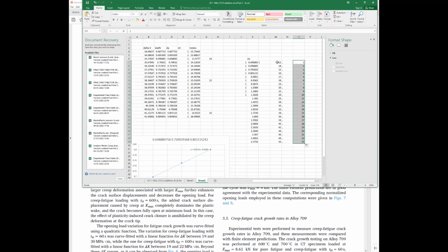So how we will do, we will release 12 elements, and then in step 1 we will apply the load to maximum, and then it will come back to minimum. So one cycle will be done, and after that, no, so what we will do is that in step 1 we will load it to P minimum value. So step 1 we will load it to P minimum, which is 900 newtons. Okay, and then the next cycle will start.